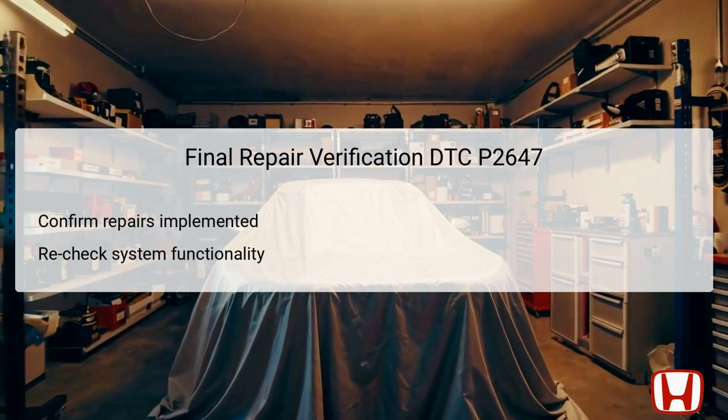After completing all necessary repairs related to DTC P2647, it is essential to verify that the repairs have been successful and that the system is functioning correctly. This involves rechecking the system functionality, which can be done through the HDS by performing the VTEC test again to ensure that the DTC does not return and that the system operates as intended.